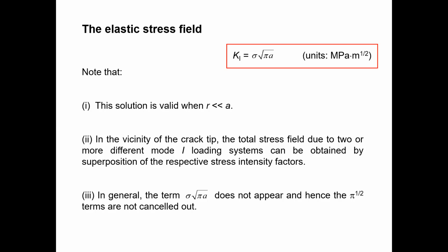So then only you can use this superposition principle. That means the stress intensity factor due to torsion, due to axial load, and due to bending, each of the three is independent of the others. This is an assumption. So you can use the superposition principle, which means you can calculate the torsional K_I, bending K_I, and axial K_I separately and get the summation.